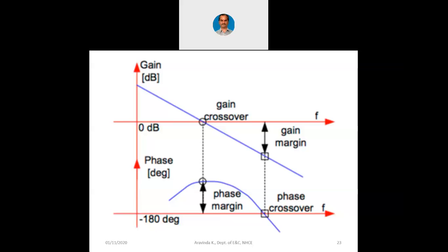Now, in these natural signals, there may be a particular frequency F that may correspond to 0 dB gain and 0 degree phase shift. Then that amplifier has no gain margin, no phase margin. Whenever such a frequency is input to the amplifier, it will keep on oscillating, and that will be a disturbance. So the idea here is that any reliable or faithful amplifier should have larger gain margin and larger phase margin. That means the circuit is reliable and faithful.